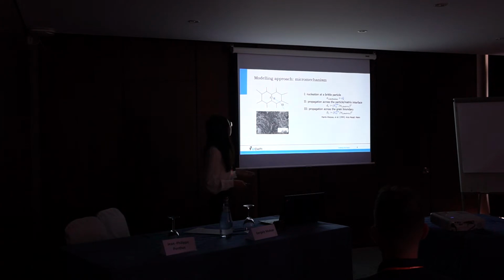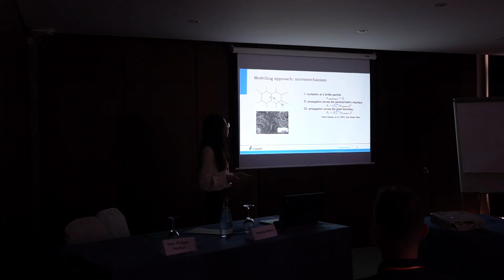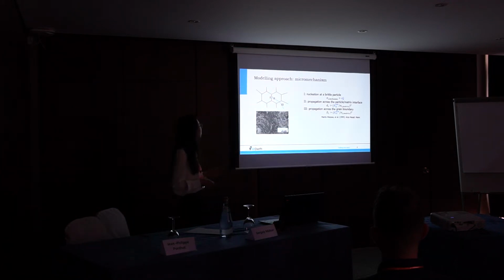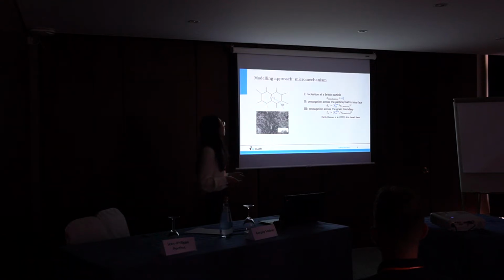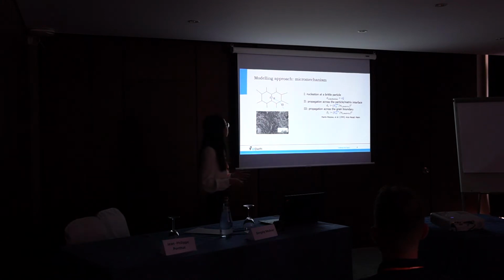Our modeling approach is based on a so-called multiple barrier model of the micromechanism for cleavage. It is assumed that there are three main events related to the initiation of cleavage. The first event is the nucleation of a microcrack at a brittle particle, which is based on a critical stress criterion. The second event is the propagation of this microcrack across the particle and matrix interface.